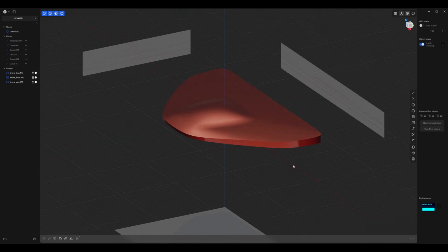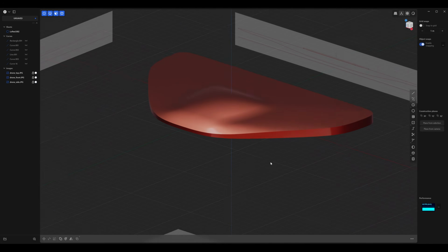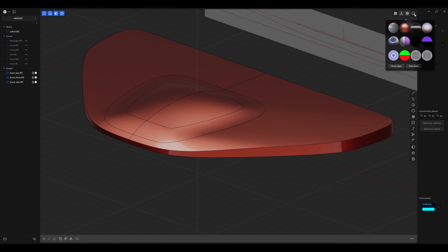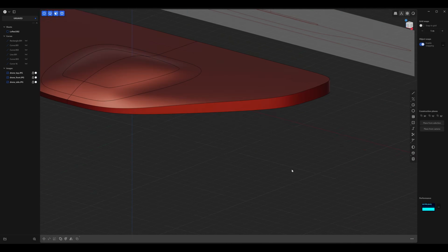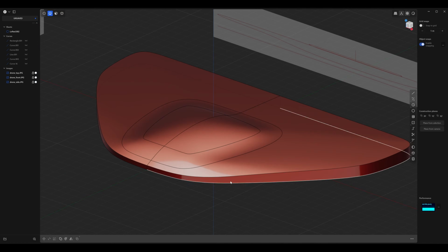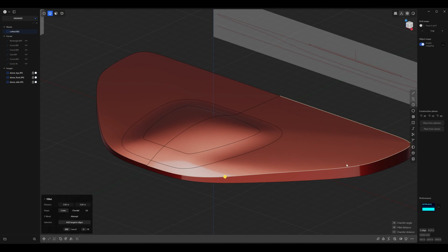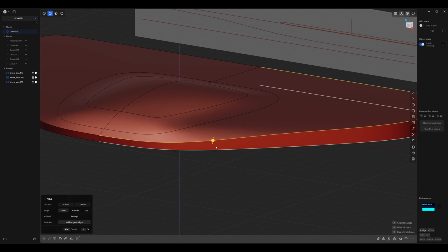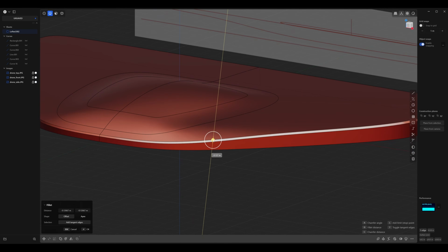Next, I'm going to show you how to create bevels or fillets with a variable radius. Go ahead and turn on your edge mode again. Make sure it's on. And then press 2. And we're just going to select one of these edges here. They're all connected, so you just need to select one at a time. And what you could do is just drag this handle outwards a little bit, or downwards in this case, and give it a bit of a sharp fillet there.